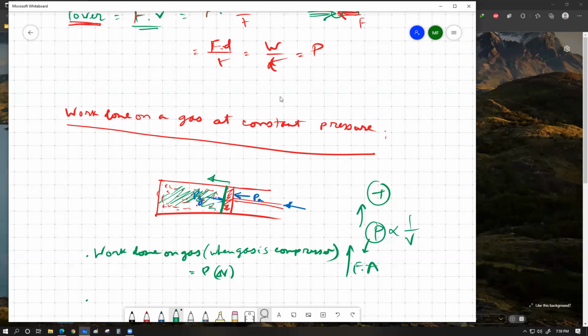the gas expansion can happen by a lot of different scenarios. One thing that we can do is apply some heat from the surroundings of the cylinder, which can penetrate through the cylinder material and eventually heat up the gas molecules inside, and that will increase the speed of the moving particles, which can lead to a higher pressure. The rate of collision would increase, and individual collisions would happen with a much higher momentum change. As a result, you can have a higher amount of force produced on the piston, and in that case, the piston is going to start to move outwards.